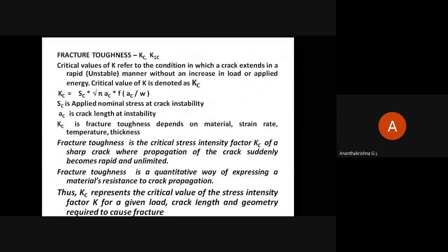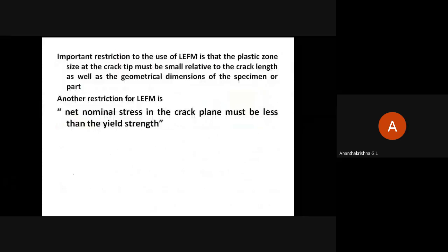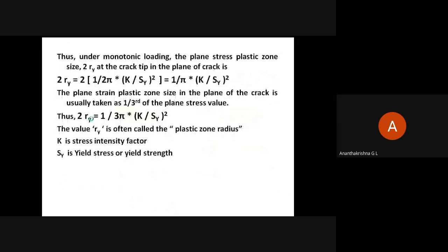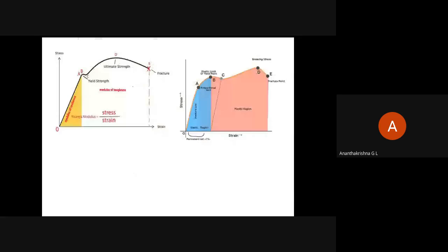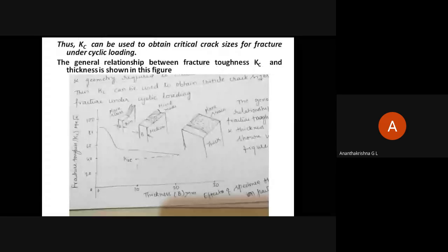Right. So here we have taken the stress intensity factor to be equal to, can you remember? Here we learned the stress intensity factor K to be equal to S into root pi into A, where S is the stress and A is the crack length. So we have learned it previously. So the same thing is applied here. That is, to come back to this discussion over here.